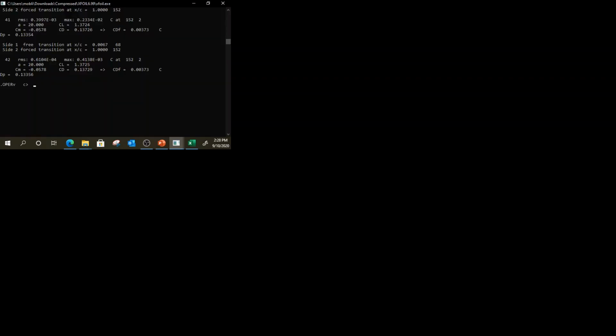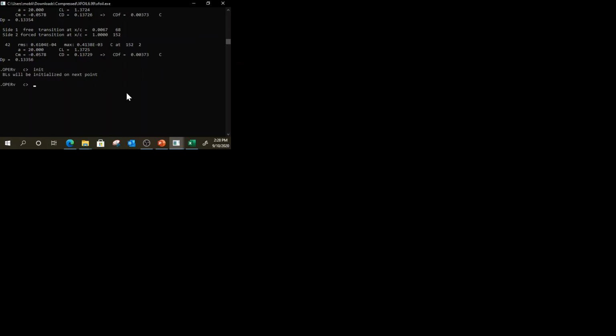So you have already passed the maximum CL range. So the CL you're going to see here must be smaller than at the lower angles of attack. To make sure that's the correct conclusion, you want to run alpha 15, for example. All it took was just 20 degrees to have a stall condition. 20 degrees is very high, actually. In a real world solution, your stall condition usually happens at 7-8 degrees with these airfoils. Okay.